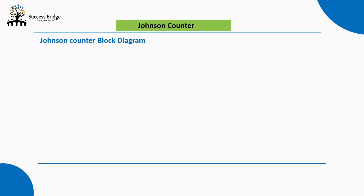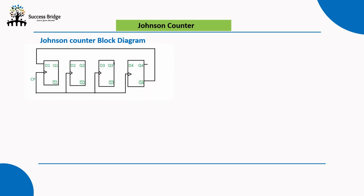This is the block diagram of a 4-bit Johnson's counter. Here the clock pulse is applied simultaneously. Q1, Q2, Q3, Q4 are the 4 states. Here we have taken D flip-flops. Here is how to determine the total number of used and unused states in a 4-bit Johnson counter.